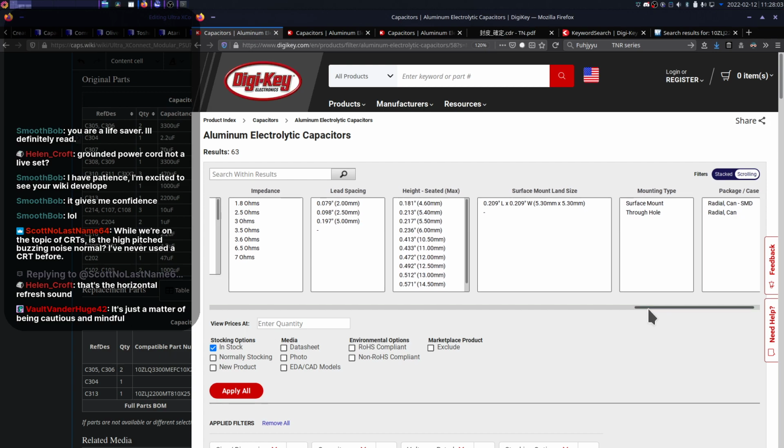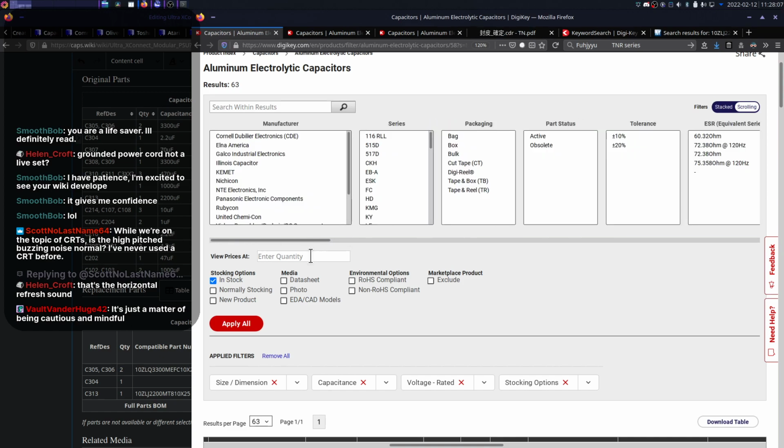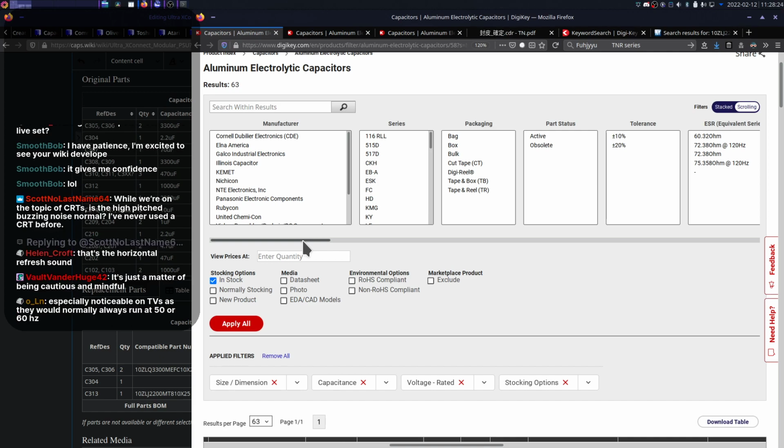But that 15.6 is pretty audible to most people. So yes, that is very real. And I have CRTs that emit sounds at multiples of that. They're harmonics, that's the word. So on my videos, I usually filter out 15.6 and I think 7.2, and that usually helps cut that down. Yeah. So it's just a matter of being cautious and mindful.